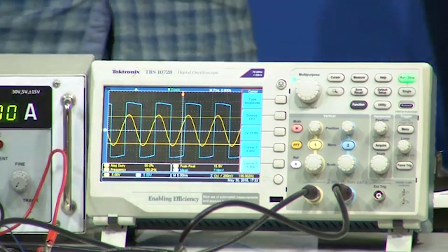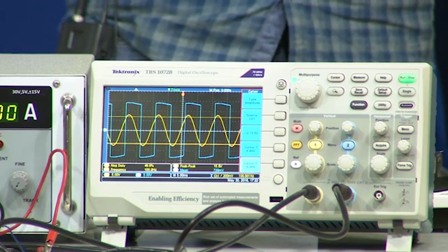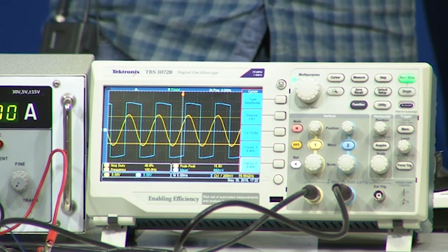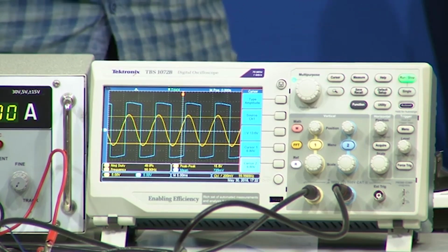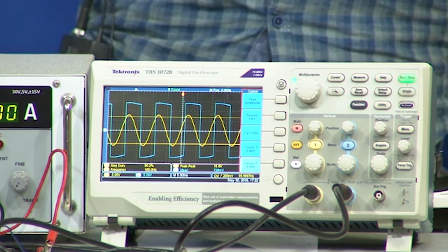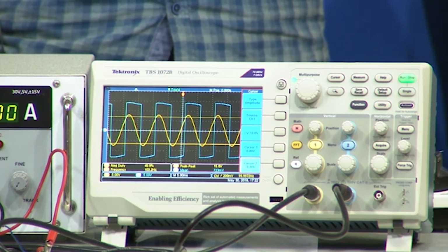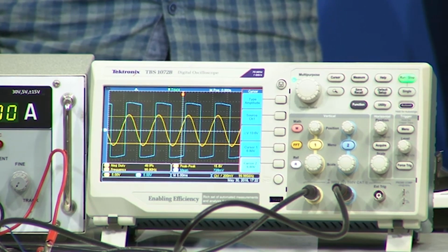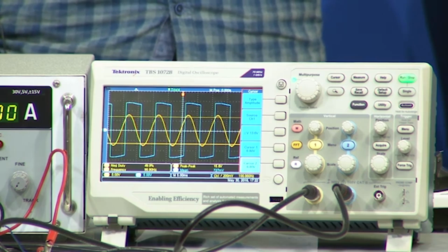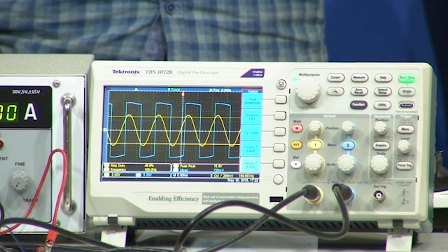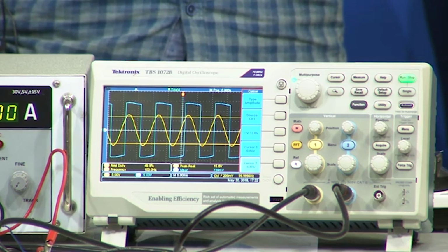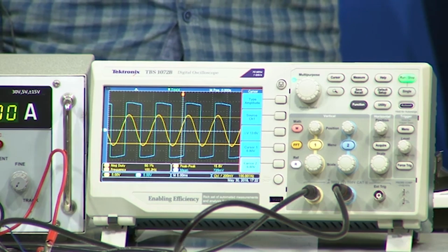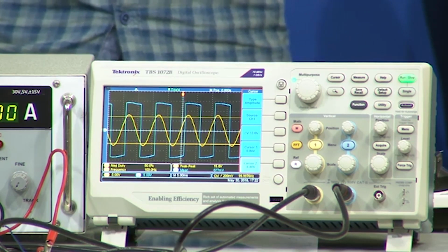So, that means whatever result we theoretically obtain for different resistance values, and whatever we have seen in the simulation, it is matching with our experimental values too. But when you compare with a normal comparator, in these cases by using two resistors we are providing two threshold values, higher threshold and lower threshold, and the threshold values entirely depend upon your R1 and R2 and what type of circuit you are doing, whether applying the input voltage to the inverting terminal or non-inverting terminal.